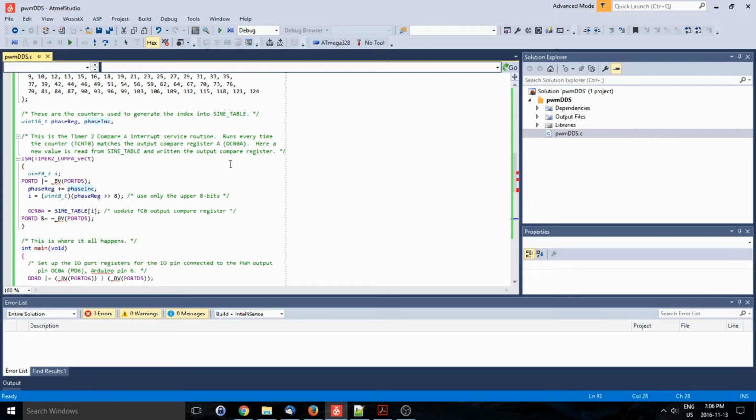I just wanted to make sure that it was capable of doing what I wanted to do and have enough processing power left over to do something else, which is, in the future case, read the serial port and process the characters being received in the serial port to generate a value for your phase inc register here.